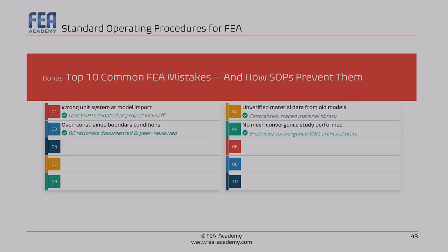The fourth one, no mesh convergence study. I know, a convergence study takes time. I know, the schedule is tight. The fix is to make the convergence study a gate. Results are not accepted without a signed convergence confirmation.